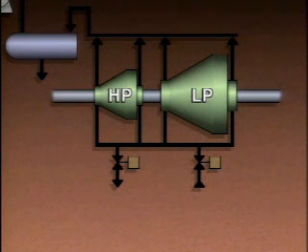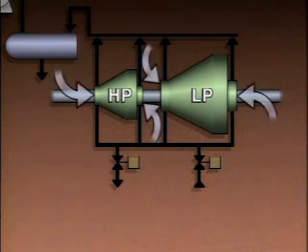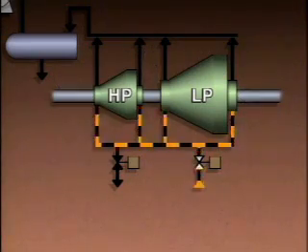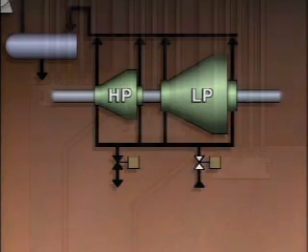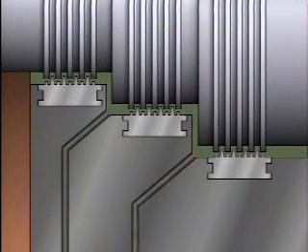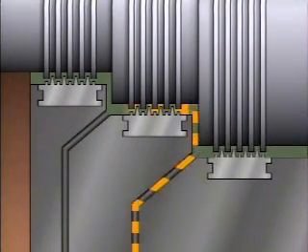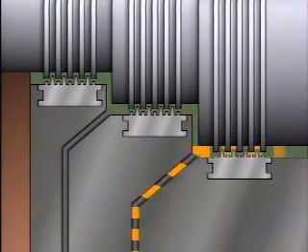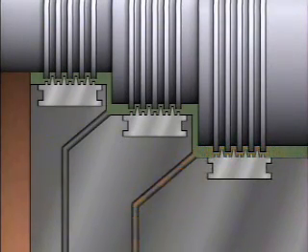When the turbine is operating at low loads and many stages are under a vacuum, outside air tries to leak in. In response to these conditions, the Gland steam supply control valve opens and low-pressure steam is supplied to the glands. Part of the low-pressure steam supplied to the glands enters here and flows toward the outside past the second seal. The remainder of the steam flows into the turbine. It's the flow of steam towards the outside of the gland that prevents outside air from leaking into the turbine. Steam flowing into the turbine from the glands presents no real problem, since the leaking steam simply mixes with steam that is already in the turbine.